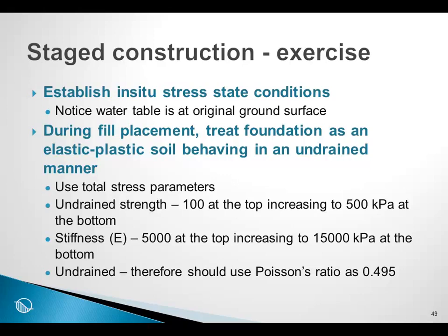In an undrained soil, when fully saturated, the thinking is that when a load is placed on the soil, the change in stress in the vertical direction will be the same as the horizontal direction. That is, water is incompressible and most of the load goes into the water, and consequently the changes in stress are the same in both directions.